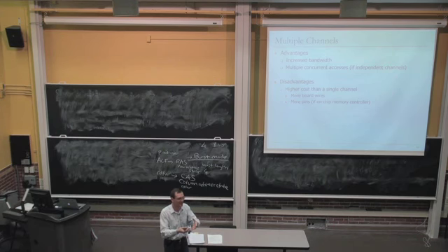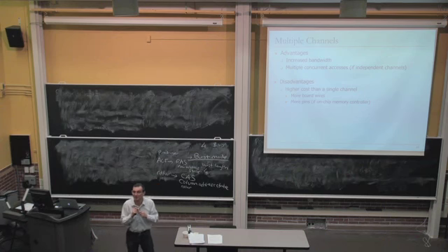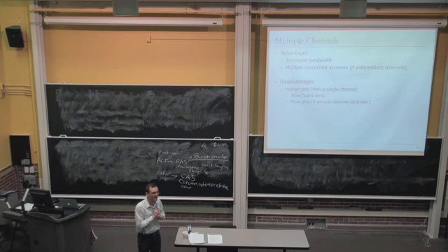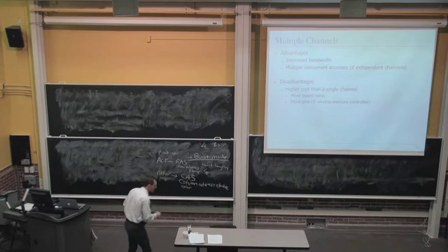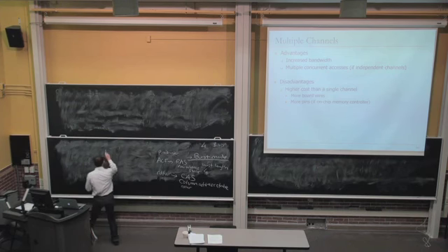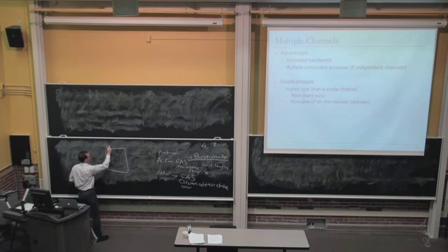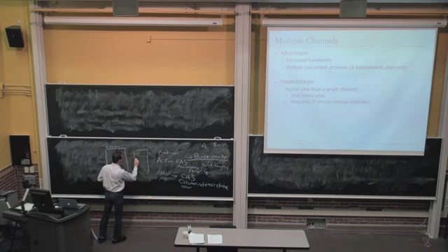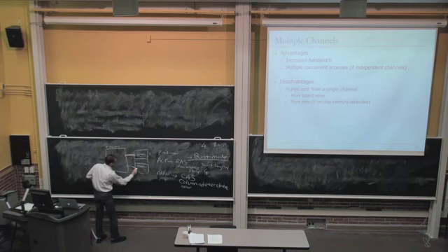They'll miss in their caches. There will be more demand for main memory bandwidth. But you cannot increase the number of channels at the same rate as you can increase the number of cores. So you have a problem, right? You have this bottleneck, if you will, between the CPU chip and the DRAM system. And the bottleneck is this.